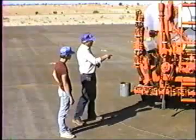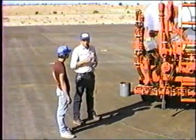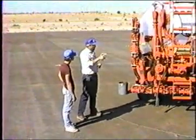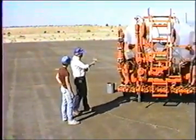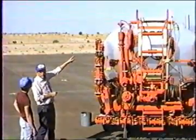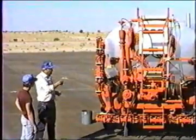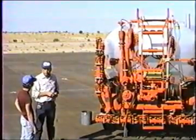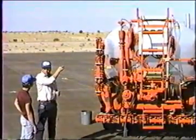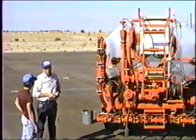Okay, we're spraying now. The equalizer valves are open, the relief valve is closed. When we come to the end of the shot, when we snap the spray bar off with the master switch, everything reverses. That is, the spray bar valves close, the relief valve opens, now it's free to go back into the tank. The equalizer valves all snap shut, so now it puts the entire circulation path back in a series configuration, so that it has to go the entire path through the bar back into the tank so that everything stays hot. And that's totally automatic.